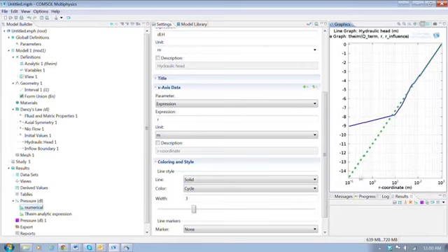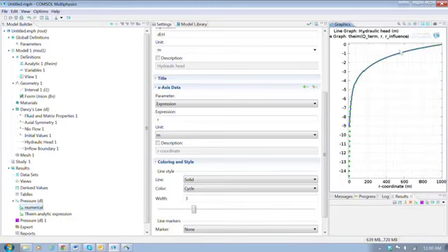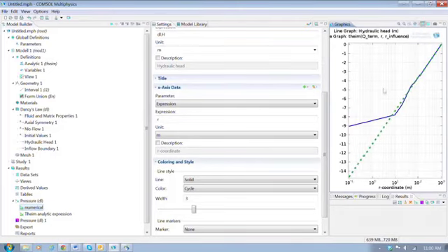So we see that these are actually quite similar if we look at it this way. If we look at it semi-log, we see right here at small values of R, the numerical is departing a bit from the analytical. And that's really a mesh effect. We can try making a finer mesh and see how that is corrected. We could also calculate the error between these two solutions and see how the error changes with the mesh.